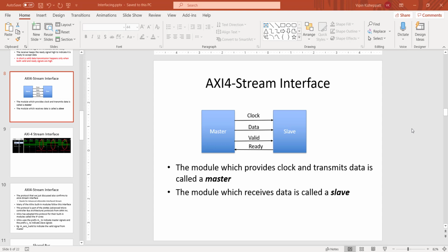Hello all. So in this project we are trying to use DMA based data transfer to our peripheral. As I mentioned before, we are going to use a Xilinx IP core as the DMA controller, but one thing that we are missing is a peripheral to which I will transfer data. So we'll make a simple peripheral. Now remember, the interface between the DMA controller and the peripheral is AXI4-Stream based. So let me give a quick overview of the AXI-Stream interface.